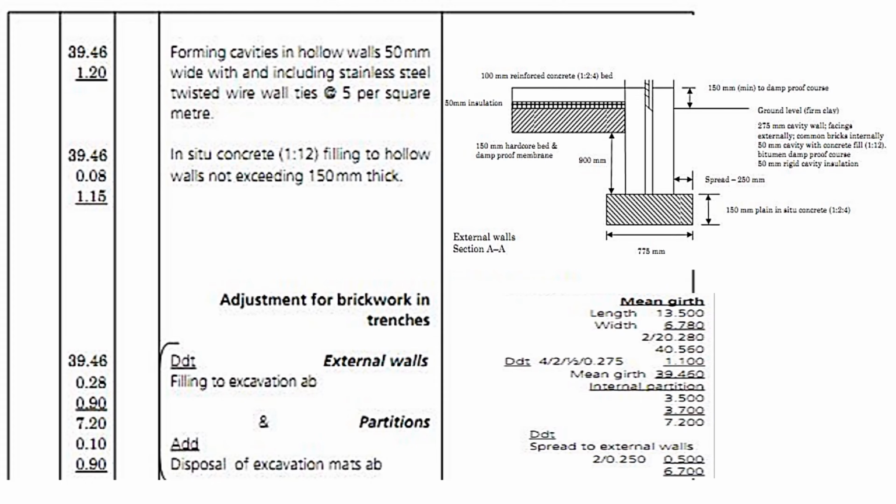We deduct 25 millimeters because we should leave an allowance between the concrete in the hollow walls and the DPC. It should be at least a minimum of 25 millimeters. So it should be 0.95. If you have another explanation as to why it is written that we should take 39.46 as the center line, that one we agree. The width should be 0.08 and the depth should be 1.15. Kindly explain it to us in the comment section. I would also want to know.